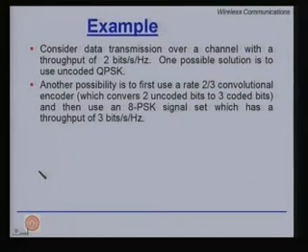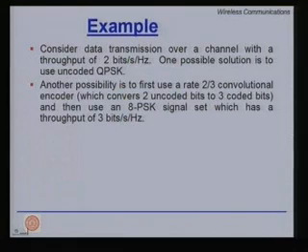The other possibility is to take 2 bits at a time and pass it through a 2x3 encoder, my convolutional encoder, right. So, now you already have some redundancy put in, because now you have one extra bit. So, for 2 bits you get 3 bits out, but we now do not use QPSK, but we use 8 PSK, which can take 3 bits per symbol. So, I did not ask for any extra bandwidth. Approximately QPSK and 8 PSK would consume the same amount of bandwidth approximately.